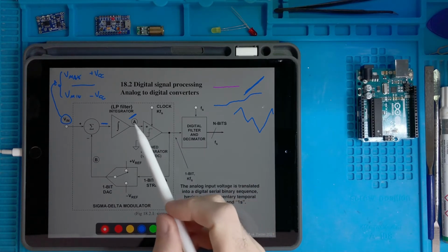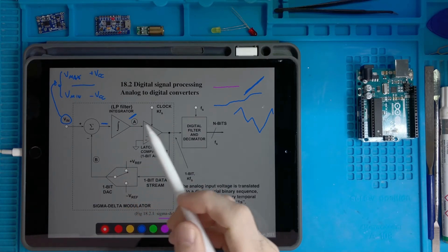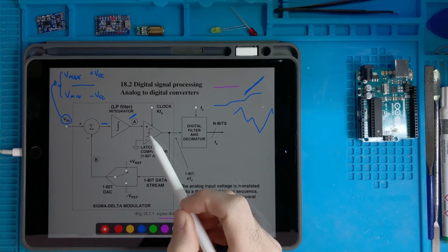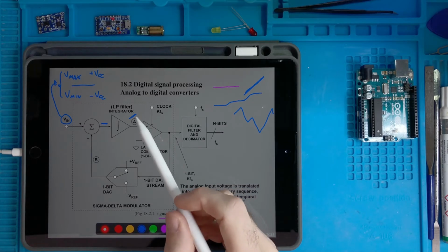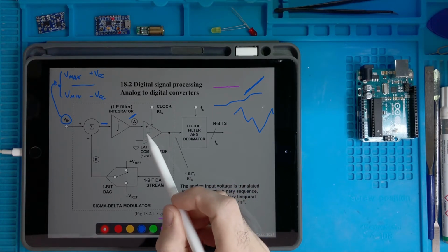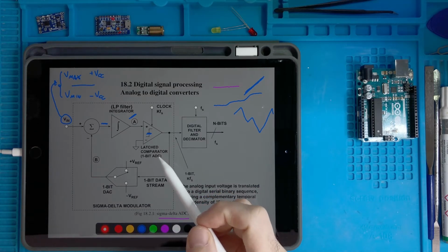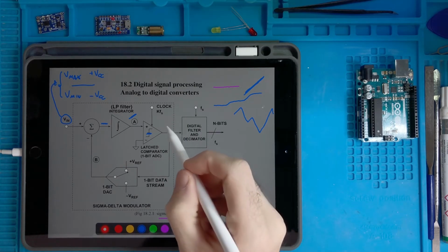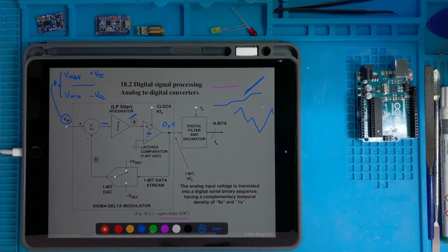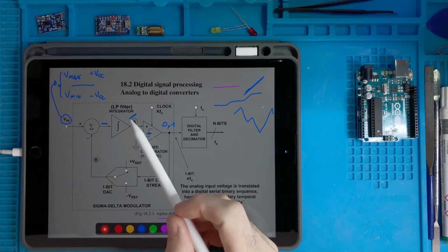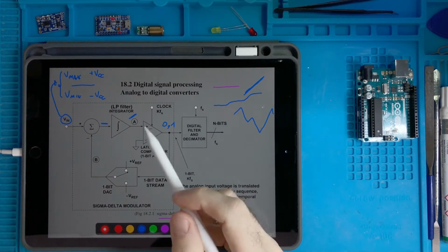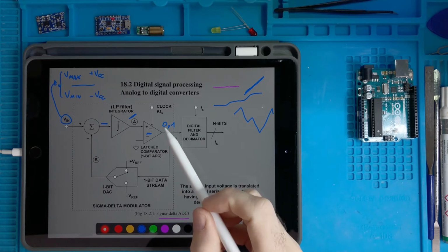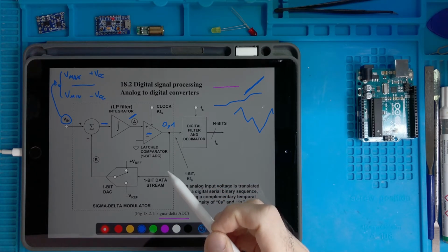Okay, so this signal, which is the result of the integration, goes inside the circuit, which is a digital comparator. It will produce a 1 if the signal here is above the threshold, or a 0 if the signal is below the threshold. So here you have either a 0 or a 1. Let's say that the signal here, according to the polarity of this little chunk of signal in time, is like this, and it surpasses the threshold, so it produces a 1.